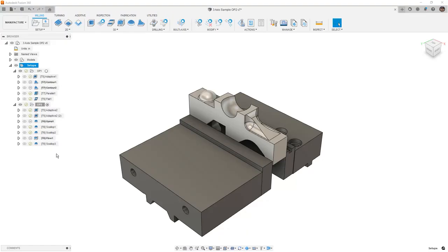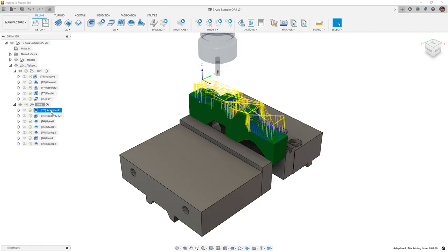If you had any difficulty creating the toolpaths, you can upload the supplied dataset 3-axis sample ready for sim. At this point, we've been using in-process stock to validate the material removed by each toolpath. And while this is a great tool to provide instant feedback on our toolpaths, it doesn't quite have the same accuracy as simulating our toolpaths does.